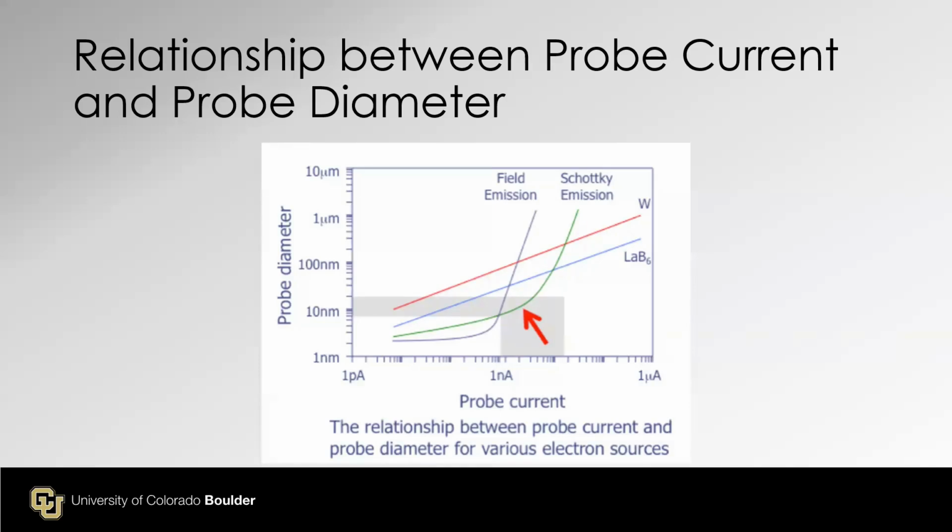You may ruin the pattern. So do we want to do it? Maybe not. After you transfer the pattern by etching or lift-off, yes, we can do that. But do you want to bring it back to the E-beam writer to characterize it? I wouldn't do that. SEM is much easier.